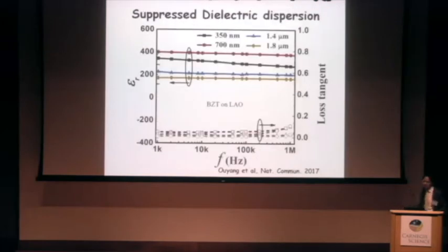And here's the dielectric dispersion. And you can see, very surprisingly, a very stable dielectric constant. And we propose a mechanism of ultra-adaptable nanodomain, so the nanodomain can really respond to the field change when comparing with the large-scale domains.